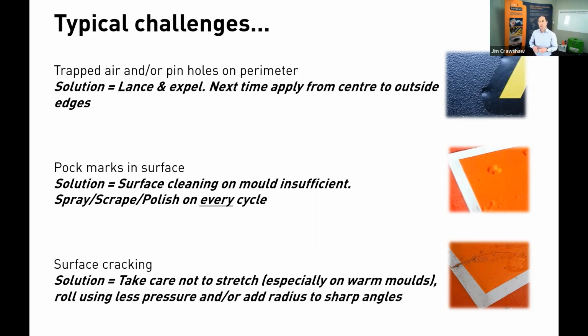The second one I'm showing there is pock marks in the surface. These are like small craters, and these could be the size of a pinhead, to the end of a ballpoint pen, or the end of your finger. So this is usually due to insufficient mold cleaning.